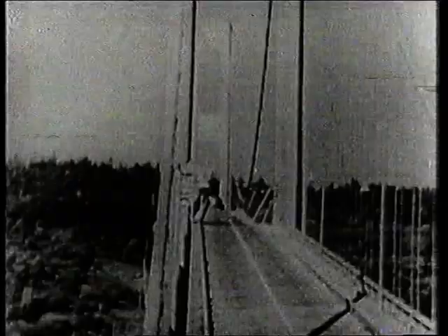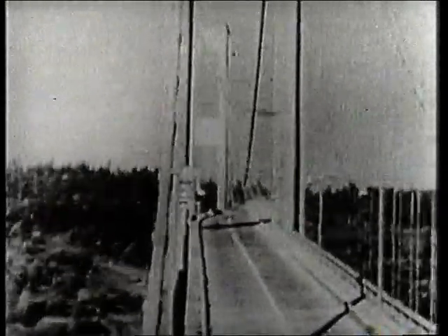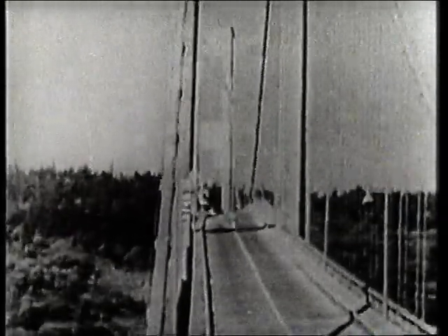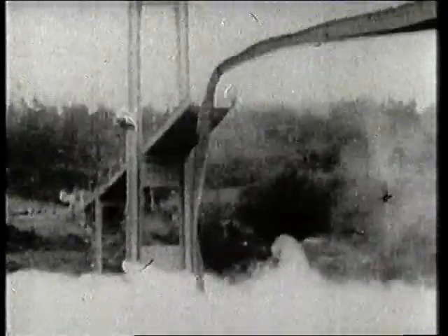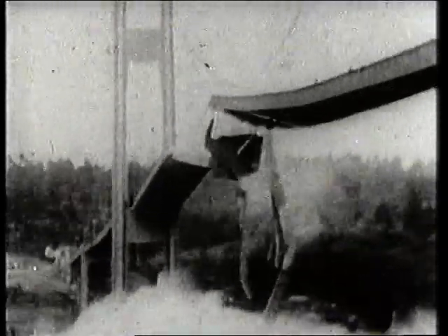Well, those displacement curves are typical of the behavior of an ideal spring mass model. But remember that all vibrating systems have their own natural frequency. And that's a problem which engineers have to take into account in what are sometimes quite unexpected circumstances. The Tacoma Narrows bridge disaster is a classic lesson for engineers in how not to design bridges. The torsional oscillations of this bridge, stimulated by certain wind velocities, eventually oscillated the bridge to failure.